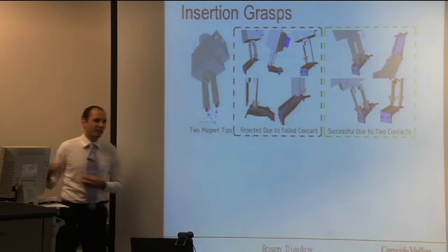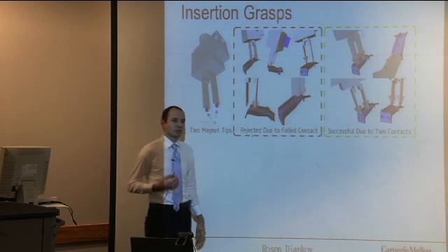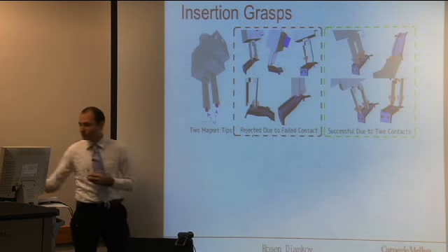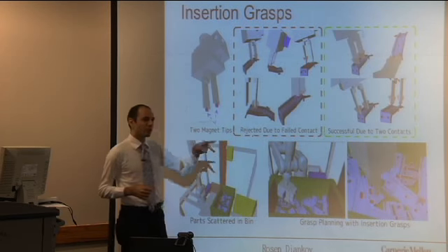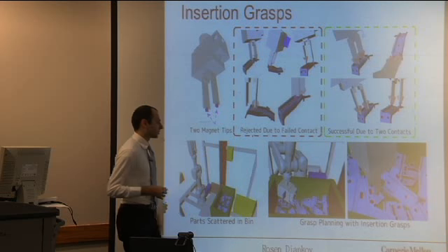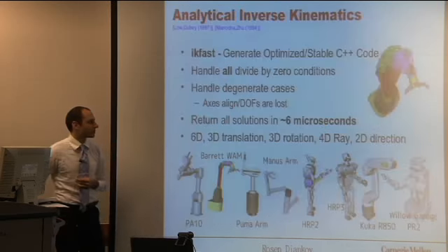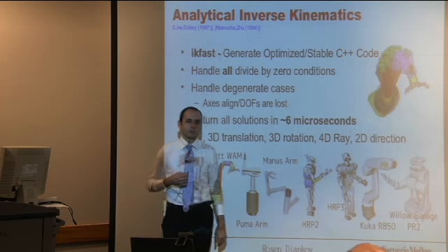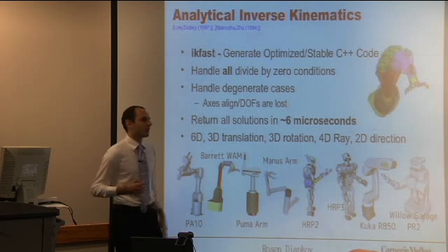Okay, so we also analyzed a third type of grasp, where in industrial scenarios it's very common for robots to insert stuff into parts. And this simple analysis just focused on having two magnetic tips try to find a really flat surface. After we build these grasp sets, we can automatically begin the planning process. Another really important part of manipulation planning is inverse kinematics.